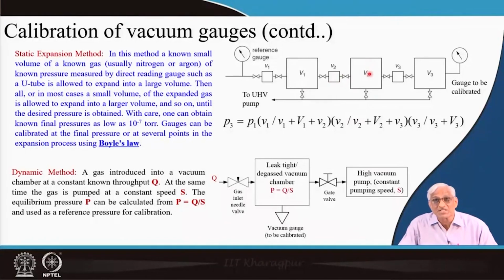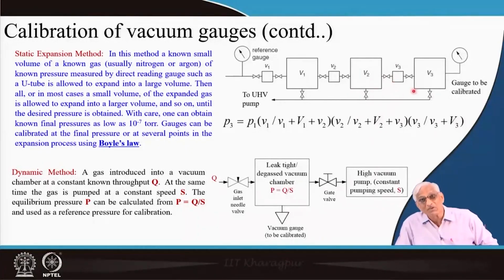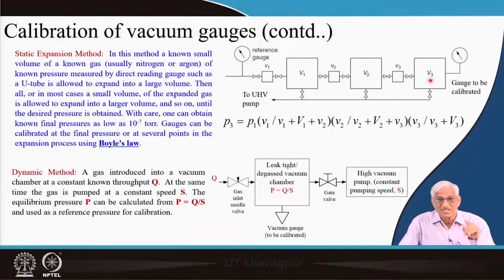That is exposed to the next stage, keeping the next-of-next stage's prelude chamber. So these three are now exposed to that. Again another pressure P3 will come, another expanded volume will come, and that will be exposed to the final stage. That way, through multiple expansions you will get a very good vacuum, but it is a calculable vacuum, not a measurable one. It is beyond measurement, and if you connect your unknown gauge, it can be calibrated using this fixed point. I will not go beyond that because it is school stuff.